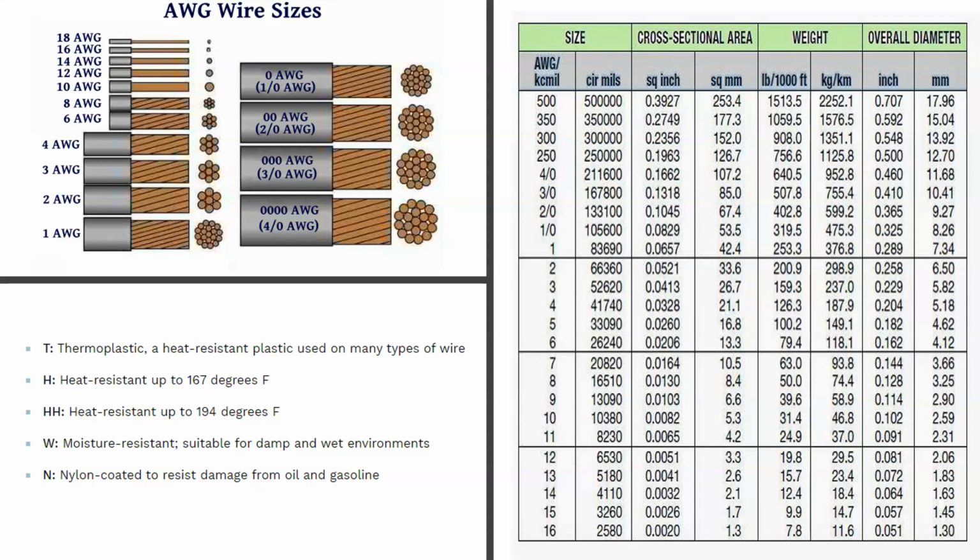And on our right here in this larger table, on our left-hand column, AWG/kcmil, starting from the bottom and working our way up, we can see we're getting larger. Then once we hit 4/0, that changes over to 250 kcmil, 300 kcmil, and so on. So once we get past a 4/0 AWG conductor, we're going to be moving on to kcmil after that, which is thousand circular mils.